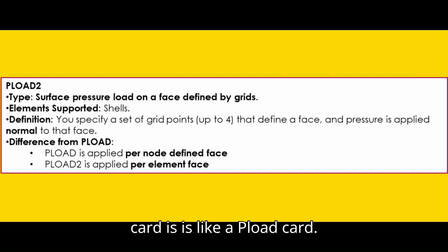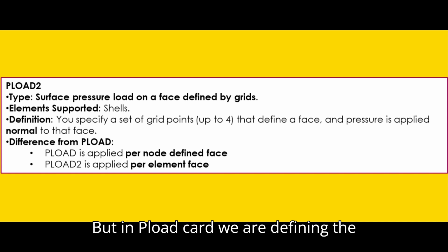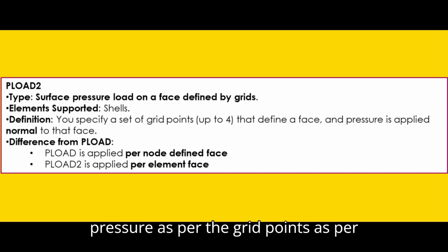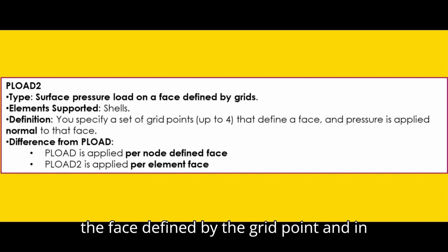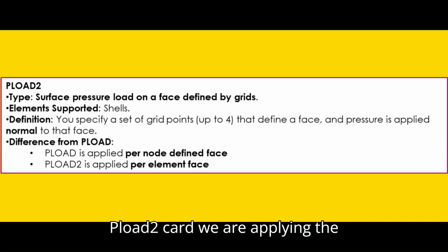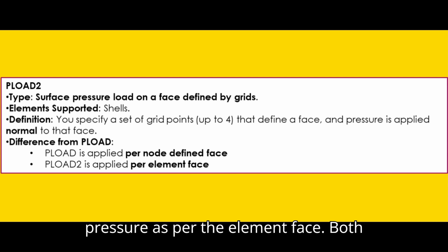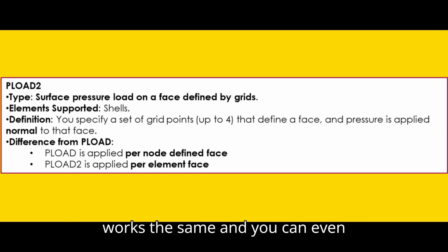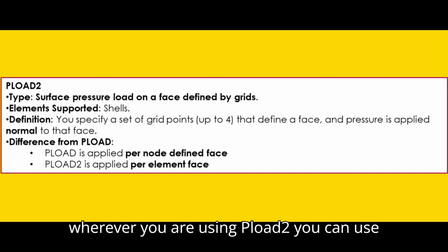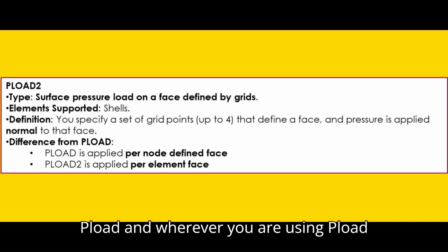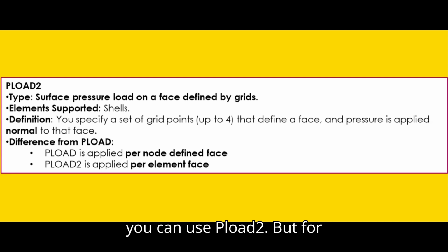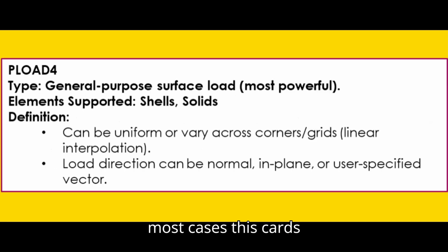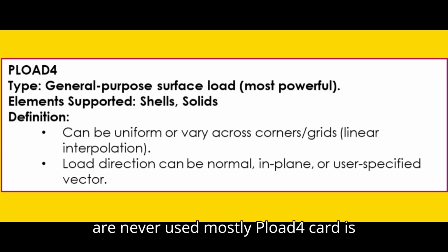Now the PLOAD2 card is like the PLOAD card, but in PLOAD we are defining the pressure as per the grid points, as per the face defined by the grid points. And in PLOAD2 we are applying the pressure as per the element face. Both work the same, and wherever you are using PLOAD2 you can use PLOAD, and wherever you are using PLOAD you can use PLOAD2. But for most cases these cards are never used.